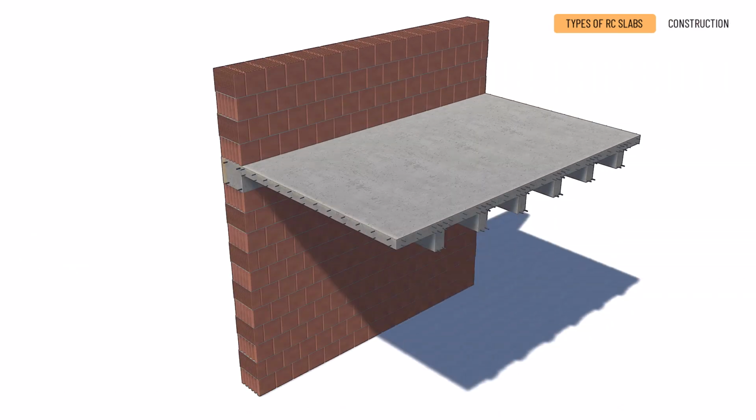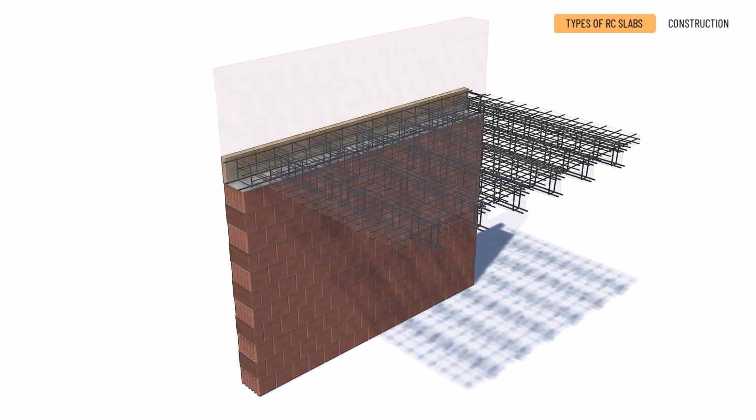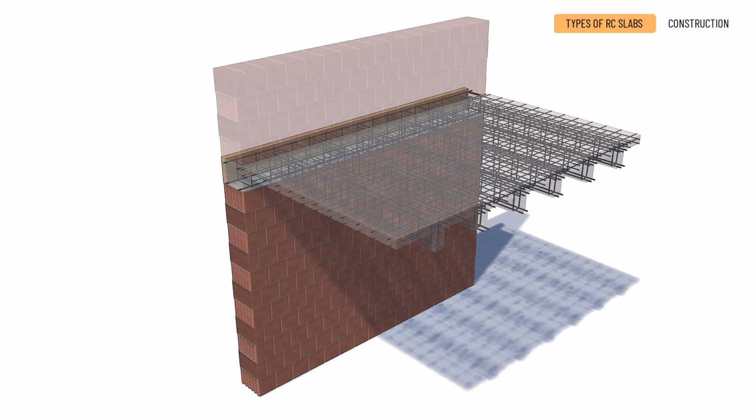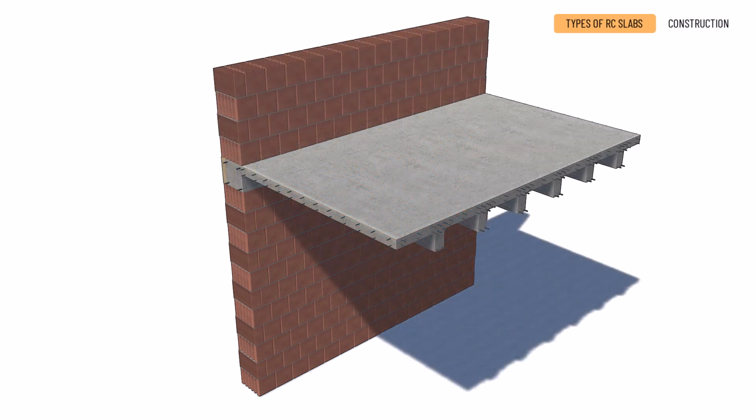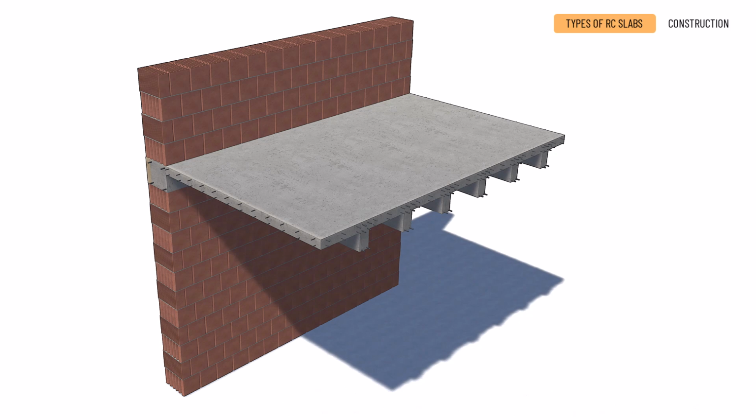In the case of a reinforced concrete slab with dense ribs, the axis spacing is only 50 to 60 centimeters, and the width of the ribs is a maximum of 12 centimeters. The upper level can be used for the floor, and the lower ribs can be used to install mechanical ducting. According to the requirement, the lower ribs can be left exposed or concealed by a false ceiling.